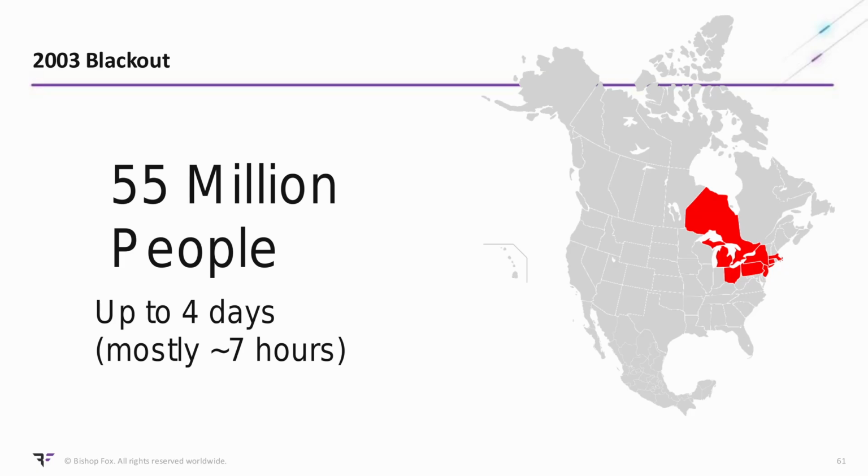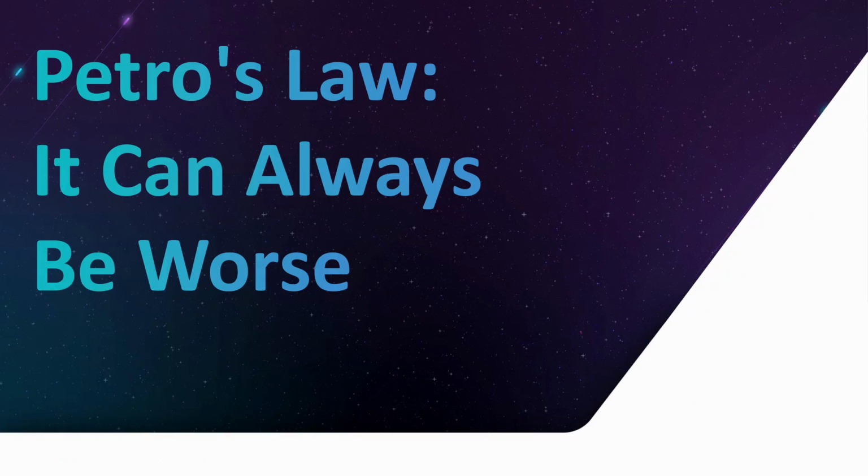How do you test for this sort of thing? You're trying to bring the power grid back up from complete blackness in a way that it's just not designed to do. And a lot of these black start generators we'd be using for the very first time, and if they don't work, then all of our plan Bs and Cs are suddenly in effect. So this stuff starts to get really scary, where the power could potentially be out for a significant amount of time over a vast amount of area. But of course, it can always be worse.